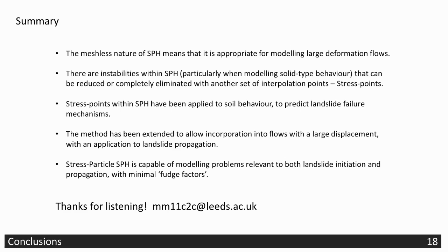Yes? In your plastic potential, in your flow rule, you had a plastic potential G. Could I just ask what G you use? Yeah, for the first case, I use an associated flow rule, and in the associated case, G is just the same as the yield function. So that is what I used for the first case that I showed you, the triaxial test. The second case, I used a non-associated flow rule where G was very similar to the form of the yield function, except that it also includes a dilatancy term as well. I can't remember the exact form of that. But it's very similar, apart from it has a dilatancy as well.